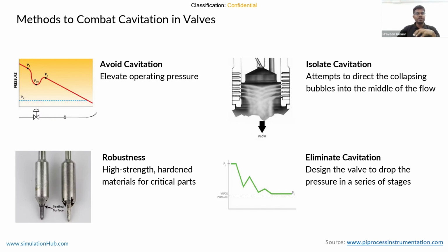The second one is robustness of the material. You strengthen or harden the material of the trim, so that it can withstand the effect of cavitation for a longer period.